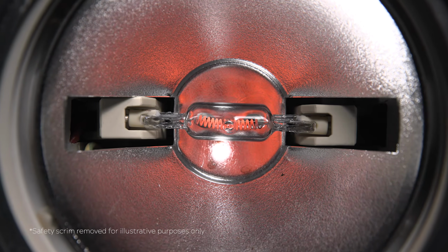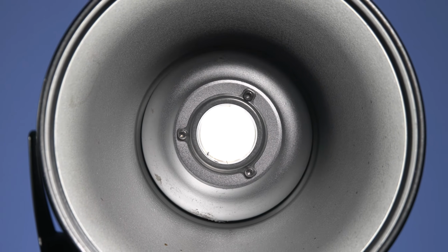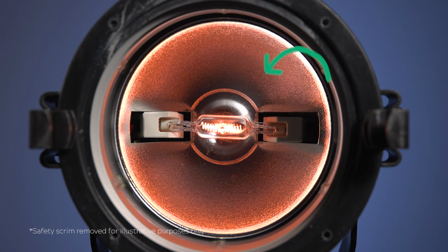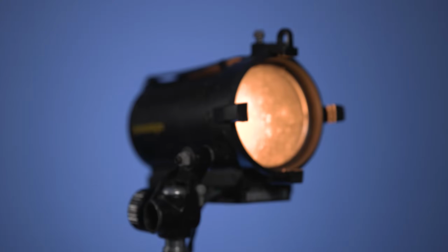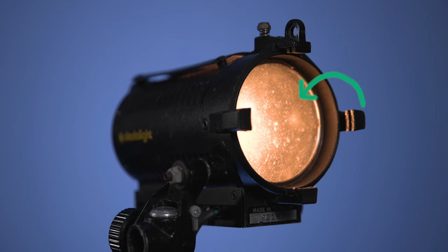In film and video lighting, our hard lights will either have a small bulb or an LED chip, which acts as our point source. To further intensify the output of the light and to provide further control over the beam, manufacturers will add a reflector dish behind the bulb to reflect and funnel all of that light outward in one direction. They may also add a lens element in front of the bulb to further control the directionality, spread, and intensity of the light.